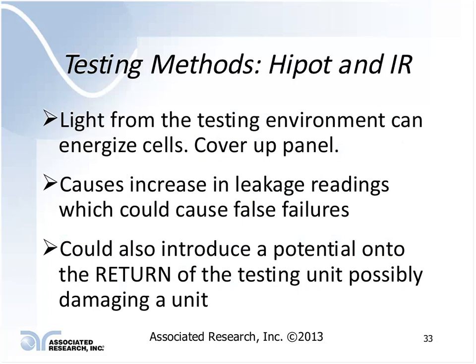It probably wouldn't even be perceptible to you unless you really bathe this thing in light. But it's just something to be aware of when you're running this test: if it is energized, it's just like a battery being energized, and then you're applying a Hipot test to it. You want to be careful.